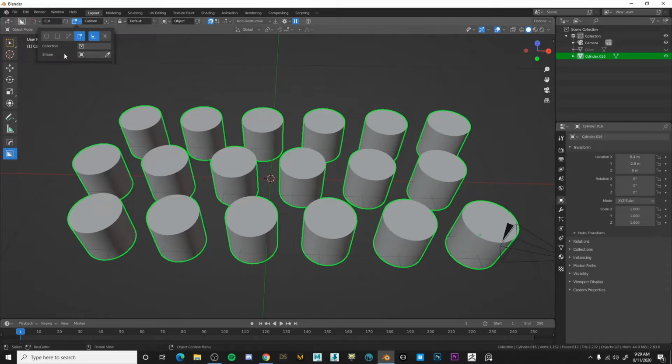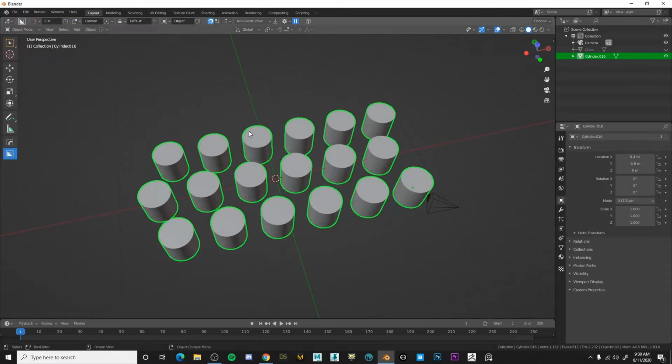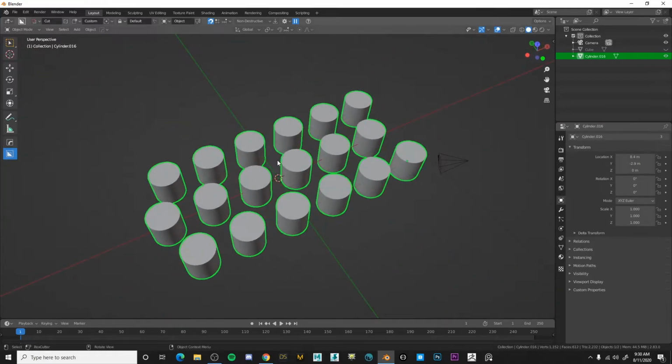By the way, you can use this color picker to pick the object, but there's some glitch to it and it doesn't work. I saw Master Zion also talking about this in one of his videos, that there's a glitch to this button, but he said he'll fix it in future updates. So what you can do is press here and select the cylinder, because this object is called cylinder here. So I'll press this, and yep, my boolean is ready.